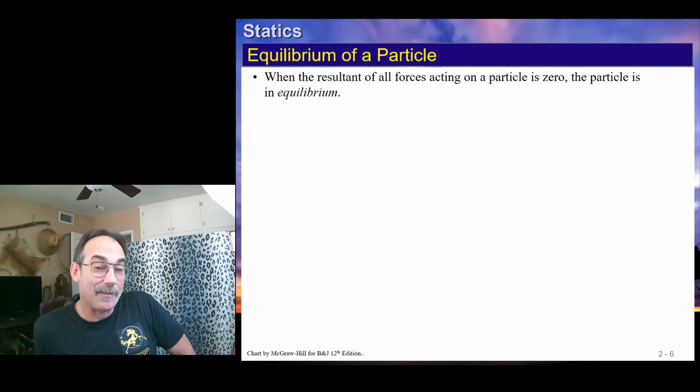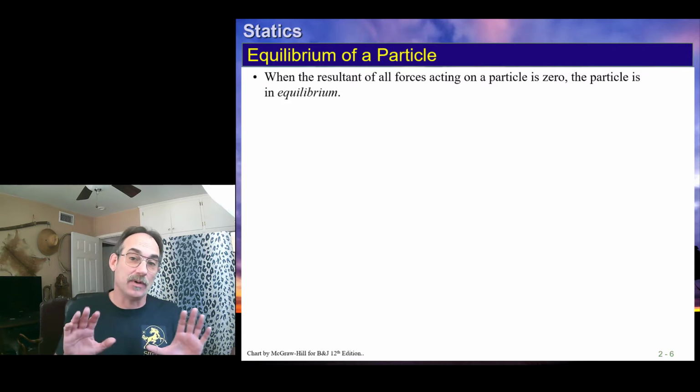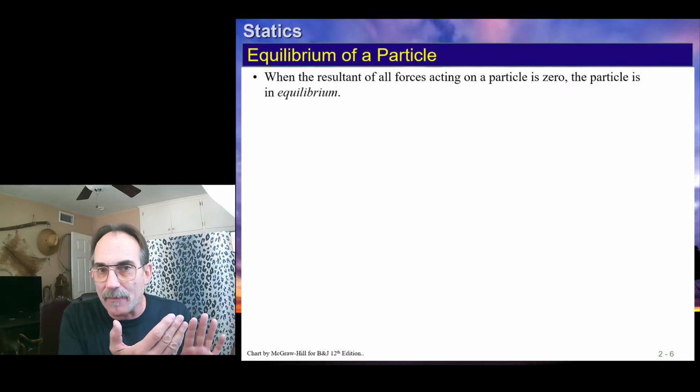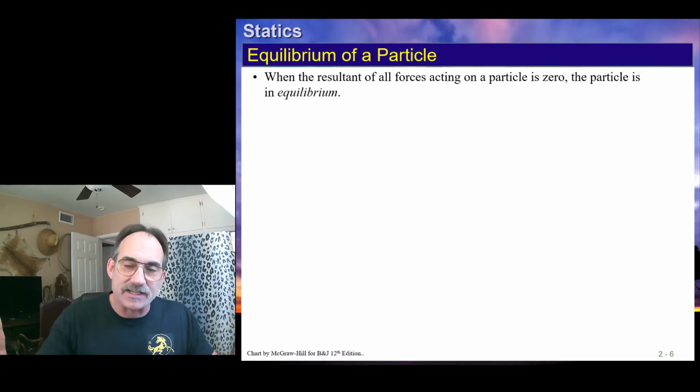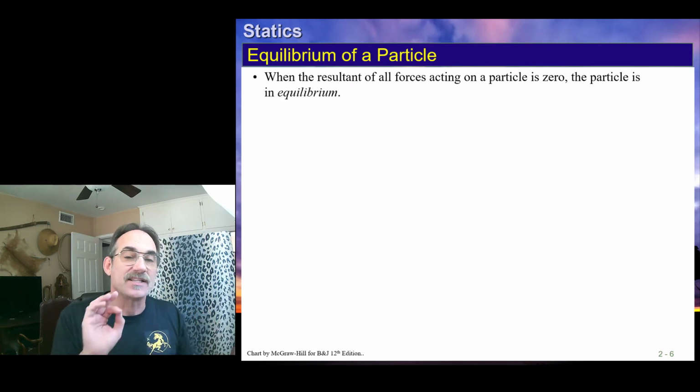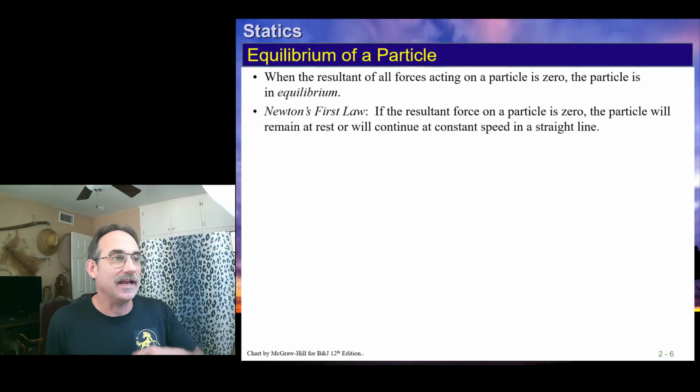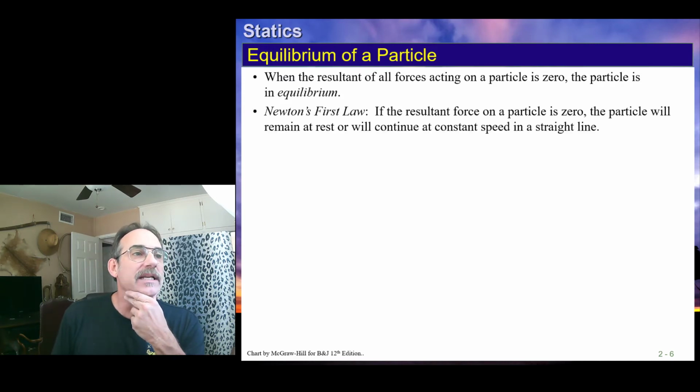Now, when we get to dynamics, in order to impose equilibrium, we're going to take the sum of the force equals ma. We're going to subtract the ma. That makes it sum to 0 again. We'll deal with that next semester. Right now, we're saying sum of the force equals 0 because we're static. It's in equilibrium, and it's also not moving. We said this.